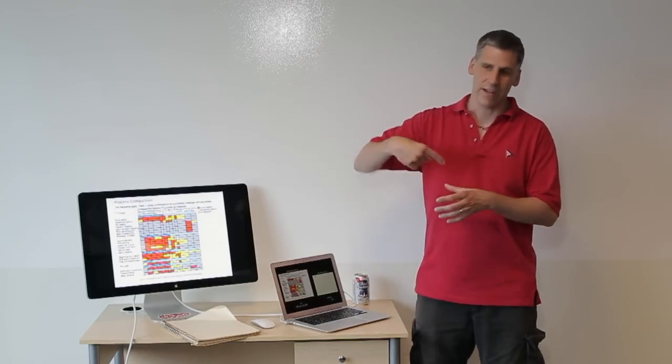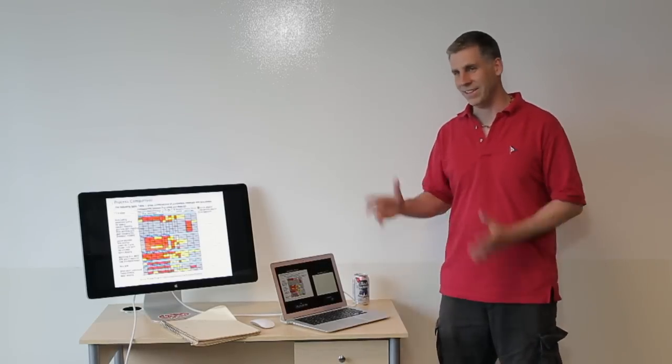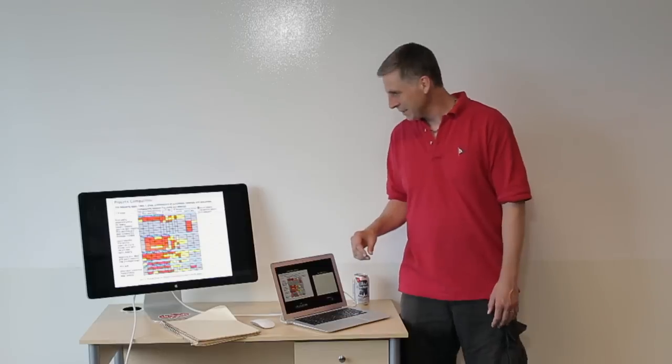What I have seen is people 3D printing the molds, so doing metal 3D printing. The challenge is, though, it doesn't leave a good enough surface finish, so you have to go and touch it with the tool, and by the time you've done that, you're sort of where you were if you hadn't done it. But it's an amazing time to be alive and see all this stuff evolve.